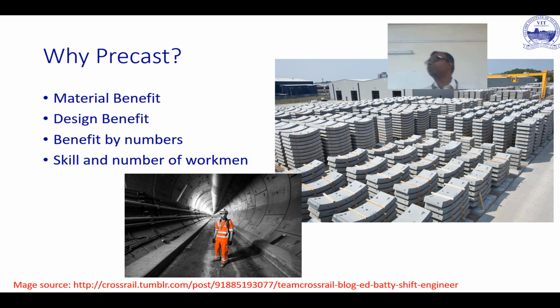So the material which you use is lesser, meaning you are getting thinner sections. Okay, and when you are going to use thinner sections, automatically what happens? The self-weight of the elements comes down. But as you make a section thinner, you find that stability becomes an issue. So that's where we design engineers are going to be a little concerned. Because of the material benefit we talked about, reduced self-weight means reduced column size, reduced beam size, reduced foundation size. You are going to find that everywhere there is a lot of savings. Okay, you will not be bothered about a very huge foundation.